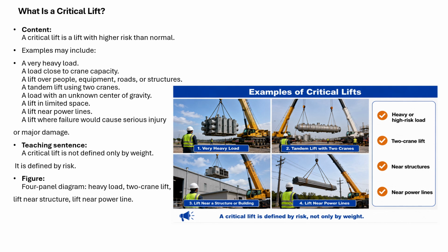A load with an unknown center of gravity. A lift in limited space. A lift near power lines. A lift where failure would cause serious injury or major damage. Teaching sentence: a critical lift is not defined only by weight. It is defined by risk.